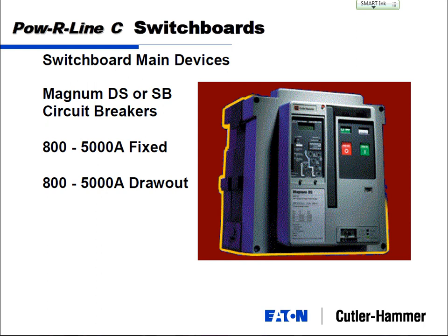The difference between the Magnum DS breaker and an air power circuit breaker is that it's designed to go in switchgear. The big difference is you can have a 30 cycle time delay before any tripping action is required in switchgear. When we talked about selective coordination and getting the downstream breaker to trip first, you can put a time delay in your main breaker or your feeder breaker, so that when it sees a fault current, it doesn't trip.